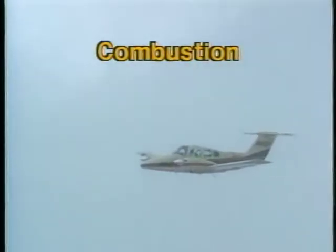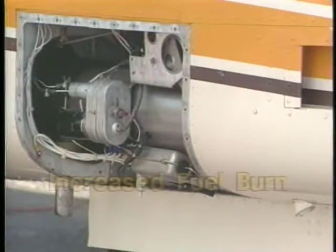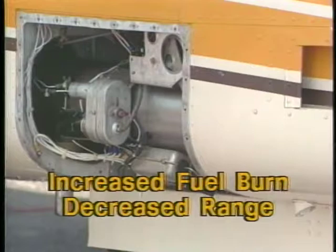The other heating system is the combustion type, which is like the gas furnace in most homes. This type of heater is commonly found on multi-engine airplanes because the location of the engines makes heat exchangers inefficient and impractical. This system uses a blower to force hot air from the combustion heater to the cabin. Although combustion heaters operate independent of the engines, they rely on the same fuel supply. Therefore, you should plan on increased fuel burn and decreased range when using this type of heater.